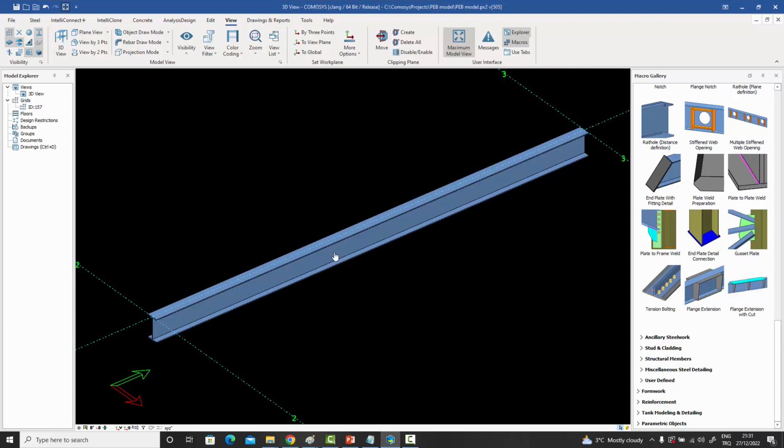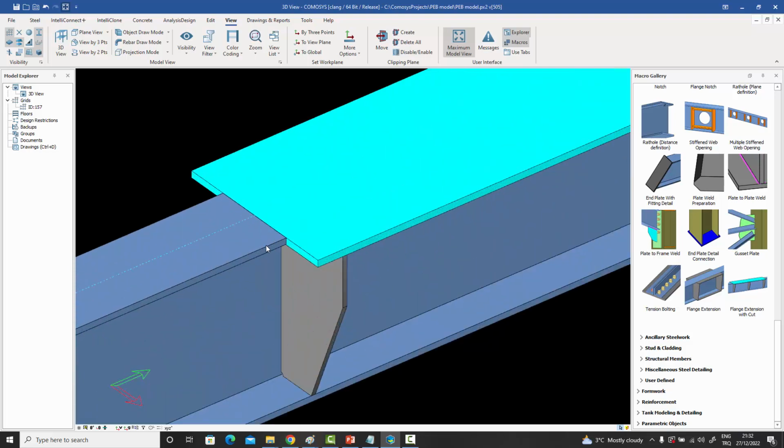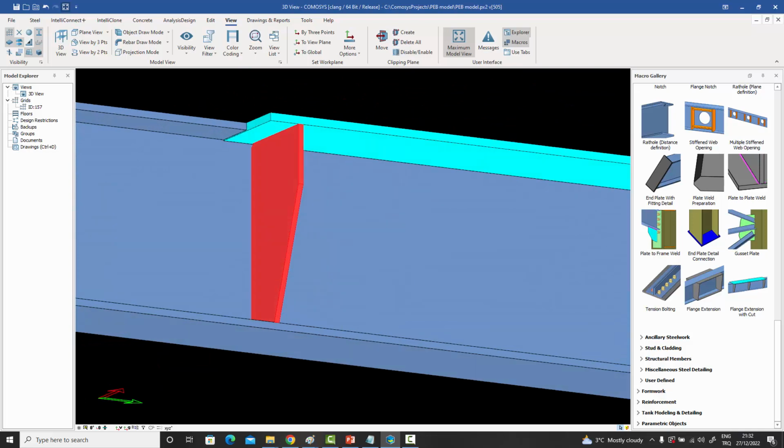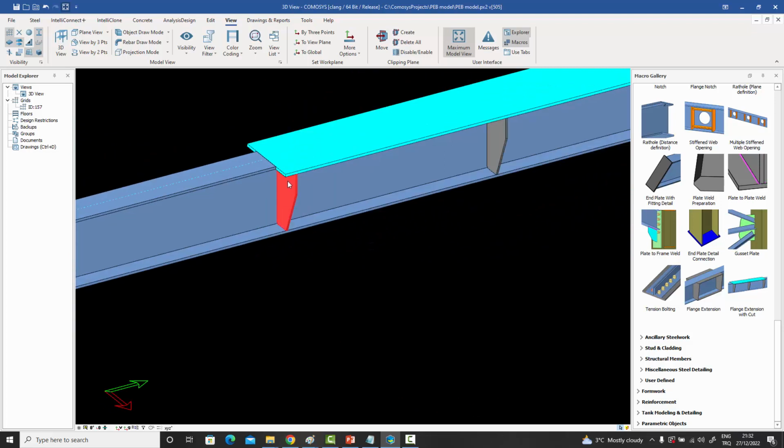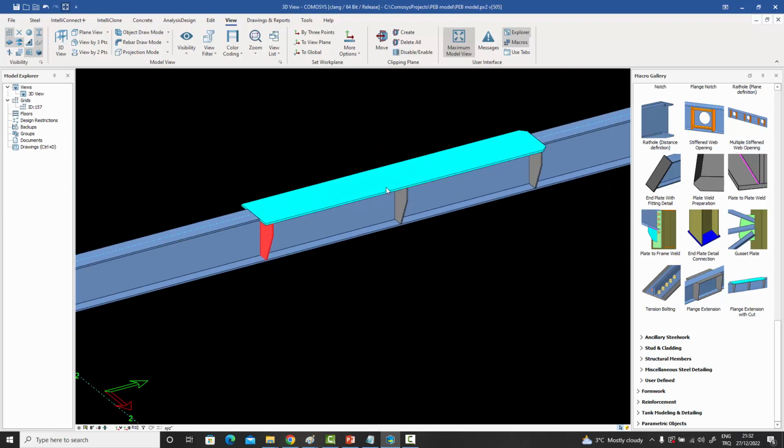All you do is you select the beam, and then you select a point on the beam, and you can do that very easily with the direct entry method, as you know. So you can say dy 2000, and that will give you a point on the beam wherever you want, basically. And then you can put another one ahead of it, and when you do that, it will create a flange extension at that point by cutting out the flange of the beam, and replacing it with a plate, one of the available thickness plates, and it will basically create this widened flange between those 2 points.